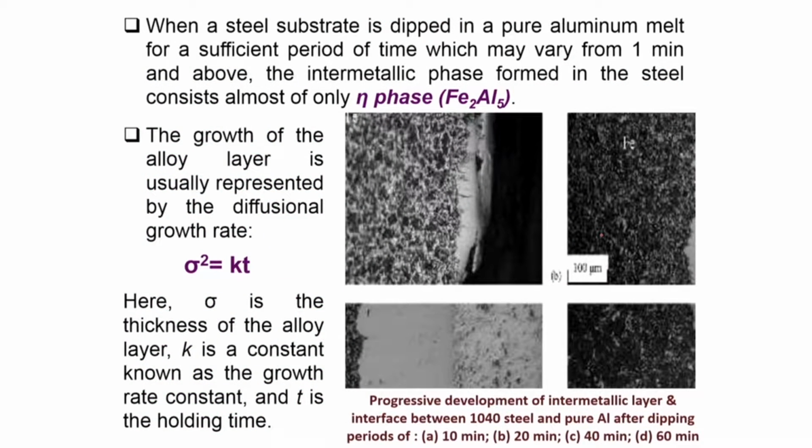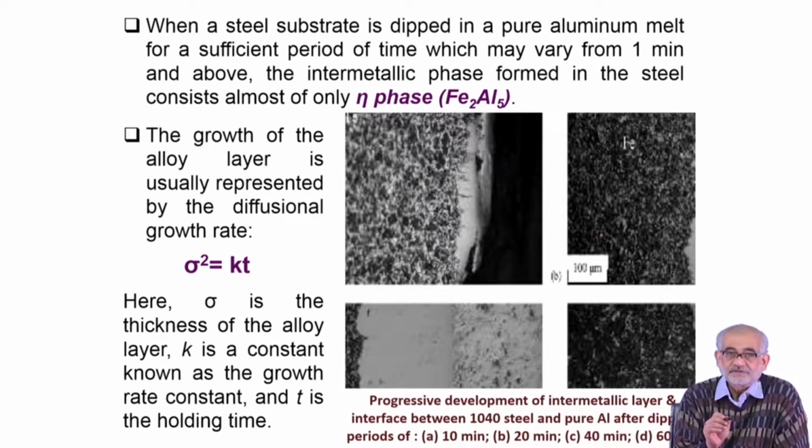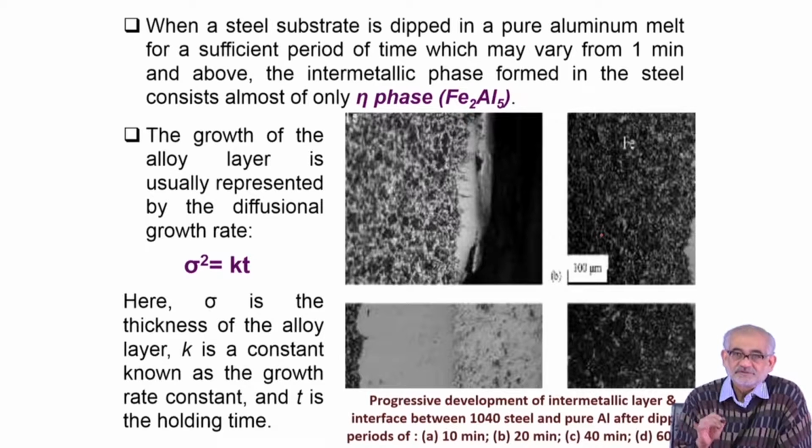So, when aluminum diffuses, see, for example, when carbon diffuses in carburizing, it does not form any compounds, it does not form cementite for that matter. It diffuses, goes deep inside, and we retain carbon, then we convert that solid solution into martensite by certain heat treatment. So, the hardness and wear resistance comes from the phase transformation product. In case of nitriding, we do form nitrides, and they are the principal reason for wear resistance, but the nitrides form at high temperature, while the application is at room temperature.